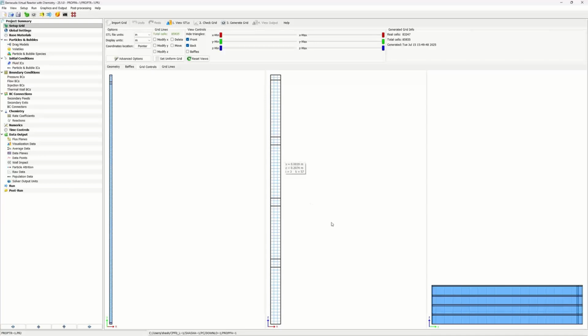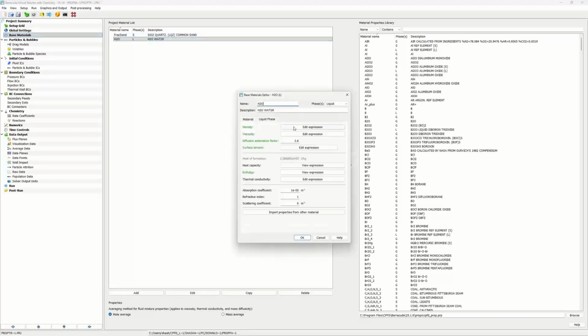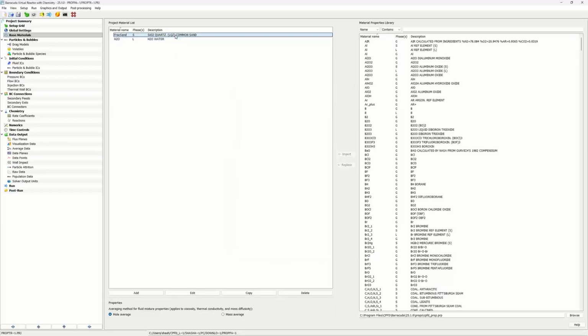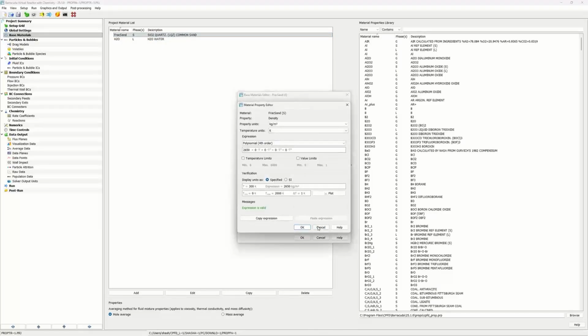First thing, if we go down here, you will see that we do have the geometry imported in. We have created a grid. In this case, we can create a nice structured grid down here. Go to global settings. We have defined the gravity direction that happens to be along the z-axis in this case. And then under base materials, we have got both our water, slick water, as well as our sand definition. So if you go down here, you see this is where the viscosity is defined, 1 centipoise. And then if you go to frac sand, we can define the density for the sand down here.